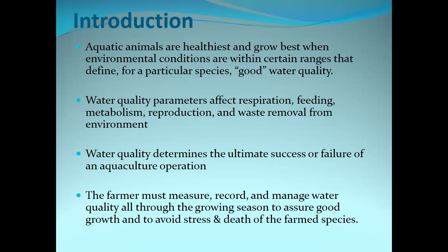But if they're producing more ammonia, that means the ammonia should have been converted because they have a biological filter, right? While the fish are producing more ammonia, there should be more conversion. But wait, you're not having more conversion because the ammonia level is increasing. So the only thing that changed is they increased their feeding. So your fish produce more waste, but the ammonia is not being converted. What is responsible for your ammonia conversion? Your biofiltration component. So now you need to go and double check and troubleshoot your biofilter component.